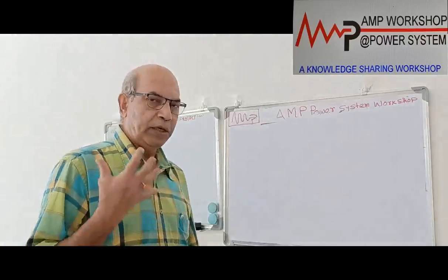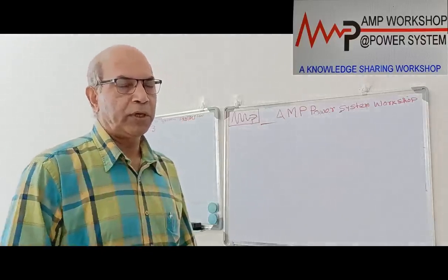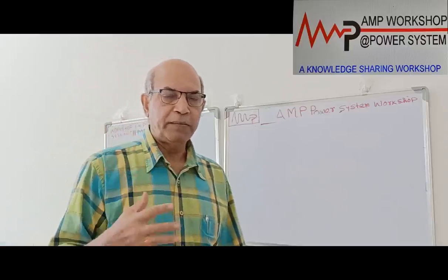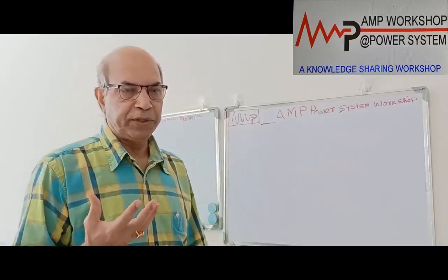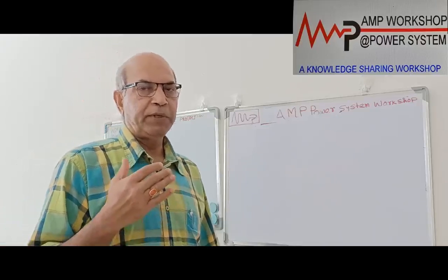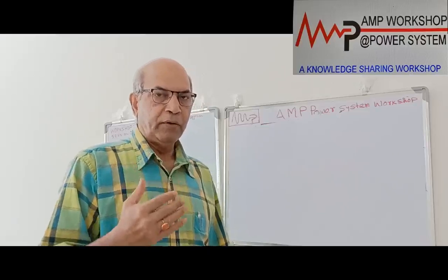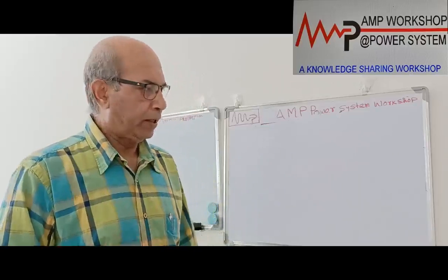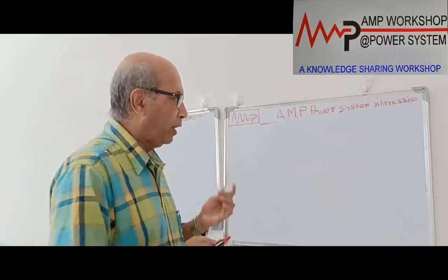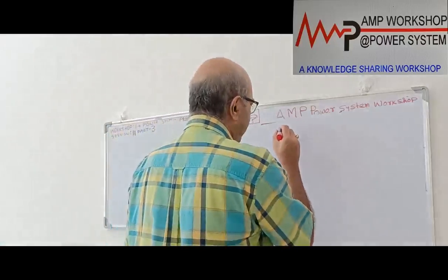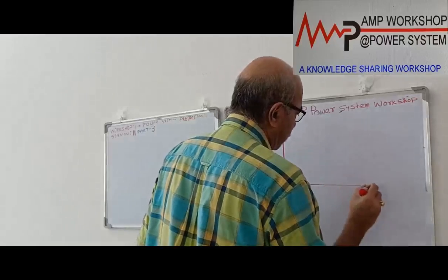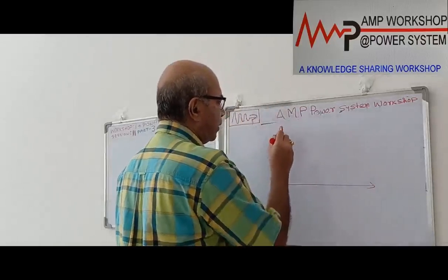In that scheme, the relay which we use is a normal conventional differential relay. The relay has a pickup setting, so we put the pickup setting. Then the moment the relay receives the pickup current from the CT, it will operate instantly. So if you see the characteristics of this relay, they will be like this for the normal conventional circulating current differential relay.